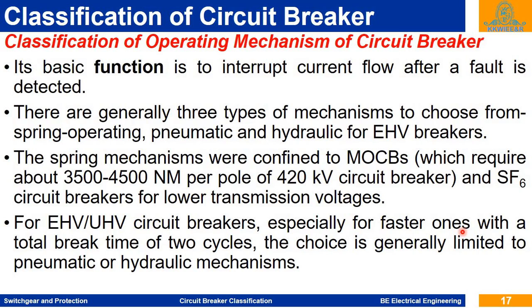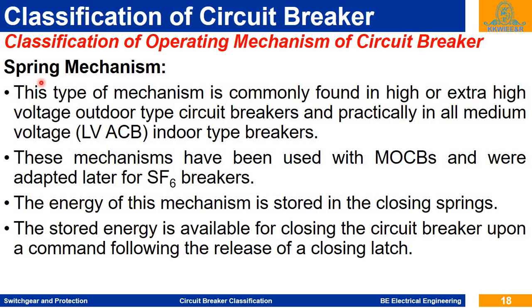Nowadays 2 cycle circuit breakers are also available in the market, so that the total break time is 2 cycles, and the choice is generally limited to the pneumatic or hydraulic mechanism, because in pneumatic and hydraulic systems higher torque can be generated while closing and opening of the circuit breakers. First is the spring mechanism.